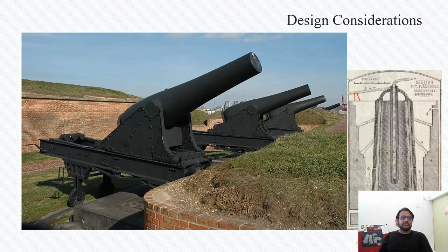Now the problem earlier, before this particular cannon came about, was with casting. Let me draw here. Let's say this is Rodman's cannon's casting process, but in a typical process you would have just a core here, and this is the part where the material would go in. So molten material would go in here, and what would happen is that this outer surface would cool down at probably the same rate as this inner surface.